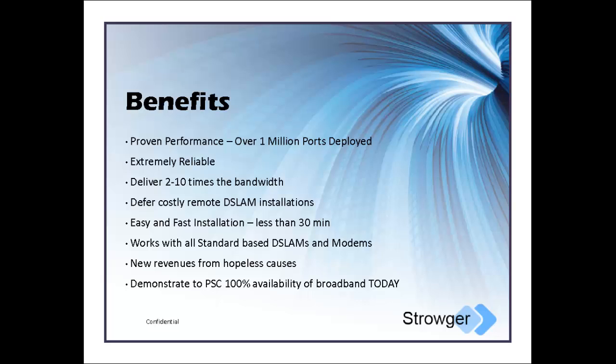If you choose the line power ADSL loop extender, the installation is just a few minutes. You stop at the pedestal, open it up, scotch lock the loop extender onto the pairs, and toss it in the back of the pedestal. This line power loop extender will reach most of your customers and allow you to do a lot of the work you need to do to reach any customer with any speed.